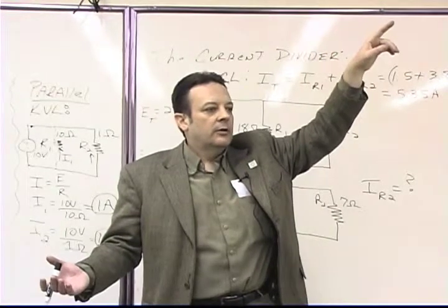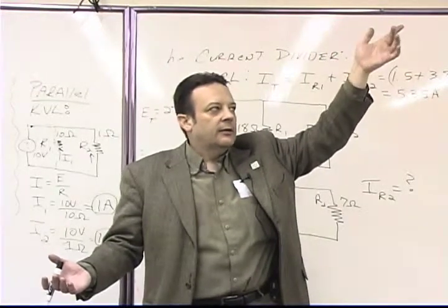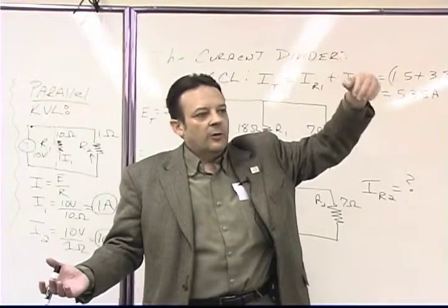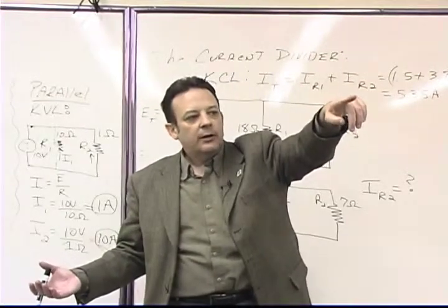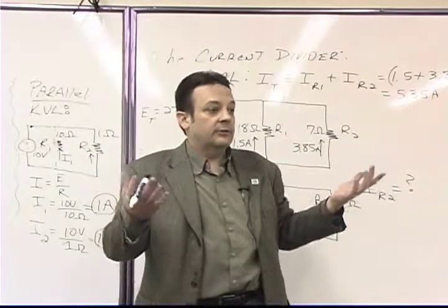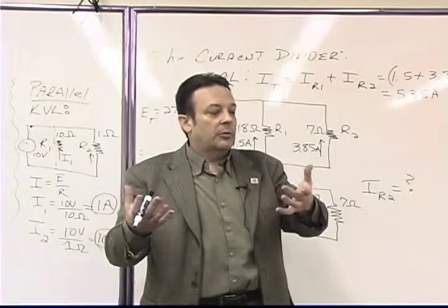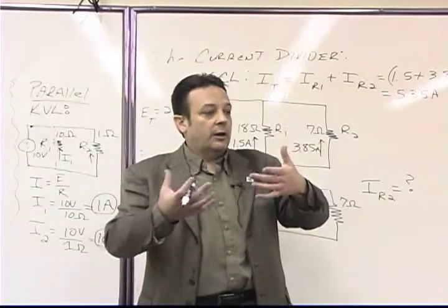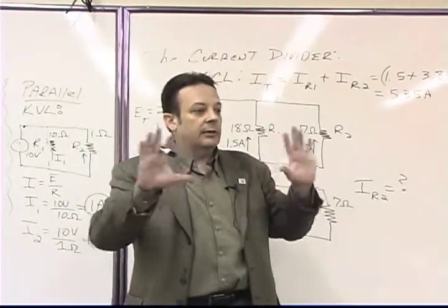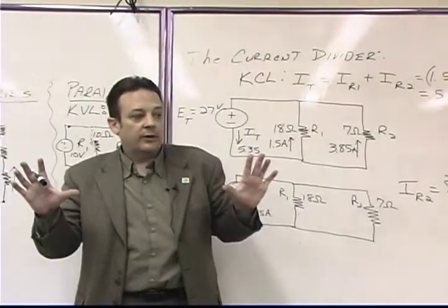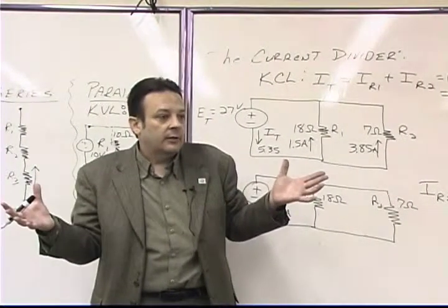So during the weekend, they can have somebody sneak over, and they can tap into your breaker live using high voltage gloves. They tap into your breaker, behind the part of the breaker that you open. So unless you're doing some kind of a preventative maintenance inspection, you're never going to see it.